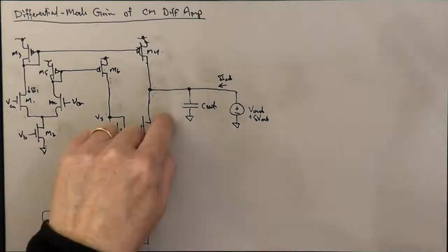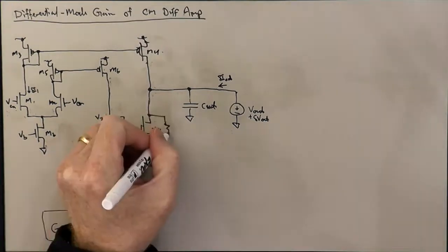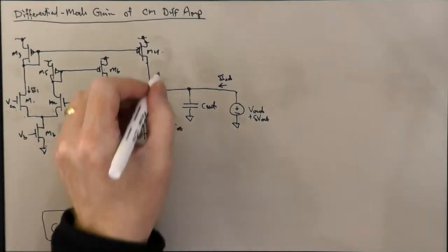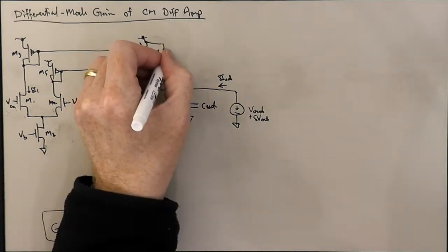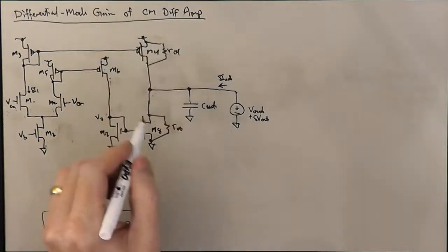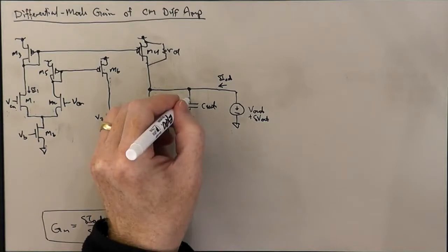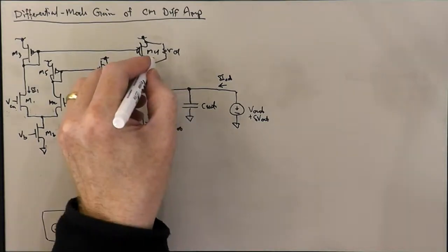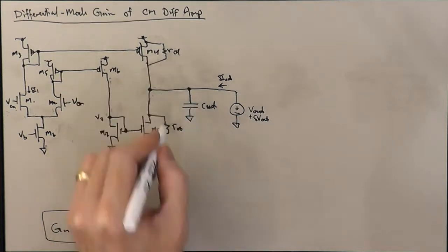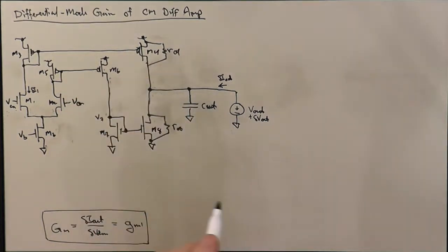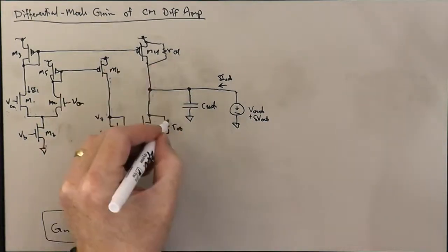Well, we could put our early effect resistors in here again, RO8 and RO4, and split now into 5 instead of 4. But since we already did split the output of the amplifier by itself into 4 and use source splitting, we know what the output resistance is of the circuit here without the capacitor.